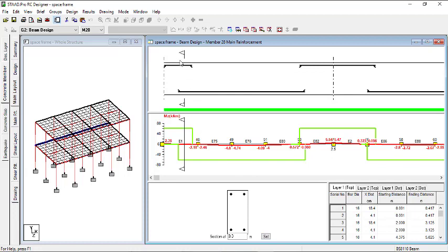At that point, you can see the section is cutting through the supports and cutting through the span. If you look at your section here, you can see you have 2 at the top, 2 at the bottom. To know that, you can just put your cursor here. You can see T16, this T16, this T16, this T16. So everything is 16 mm.